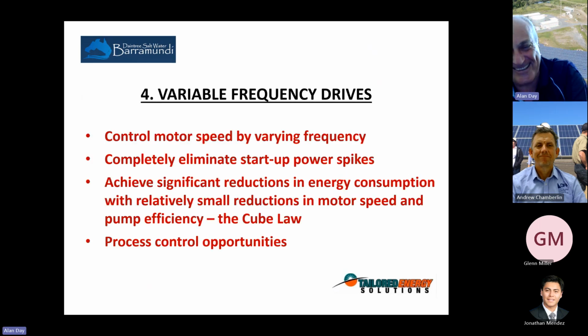Moving on. So variable frequency drives or variable speed drives provide, basically, a process of controlling the motor speed by changing the frequency. It has a number of benefits. It completely eliminates the startup surges, and if you use it to slow the motor down, and we'll look at this, it can achieve significant reductions in energy use.